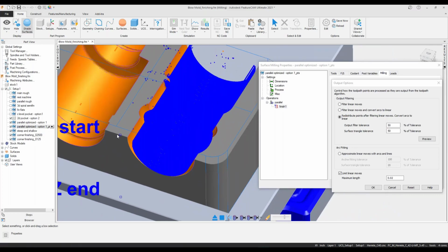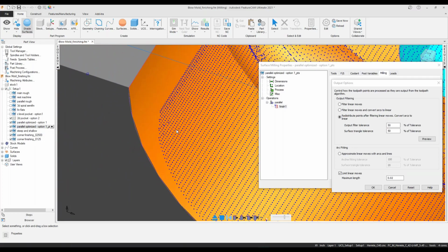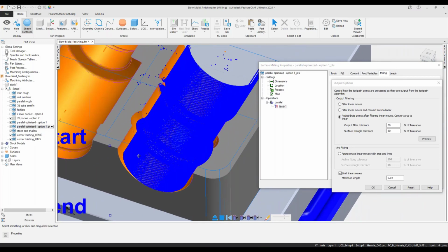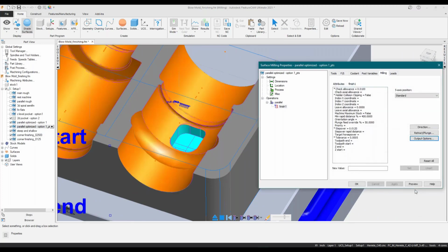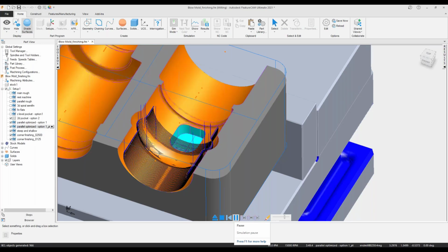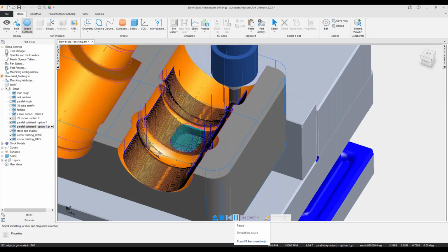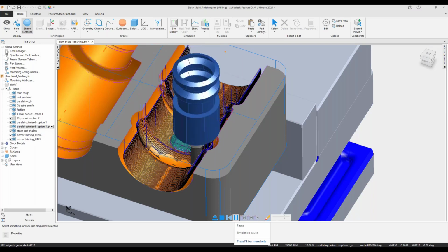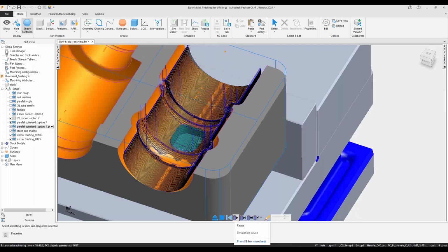But we're cutting this other opposing side. If we look, we can see the amount of points that I've added to this toolpath, which is going to give me a much better surface control or surface finish. Okay, so let's just hit OK on that. Let's do a quick preview. And by naked eye, you're not going to see it really too much in the preview side, but I left the other options on in this toolpath like we did on the other side of the part. Okay, so it's going back, adding that perpendicular pass or optimized. And there we go.